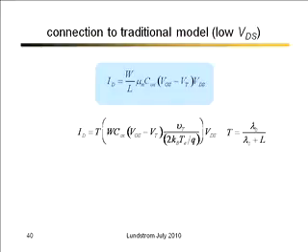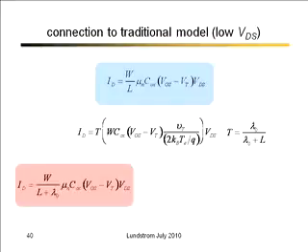All right, how do we do that? Well, it's actually quite easy. We know that transmission is mean free path divided by mean free path plus the entire length of the channel under low bias. Okay. So if you do that, just do a little bit of algebra and rearrange things. What you'll find is that the current is proportional now not to W divided by length, but W divided by length plus one mean free path, and everything else is the same. All you have to do is to take your traditional expression and replace L by L plus lambda. And you saw that in Professor Dada's lecture.